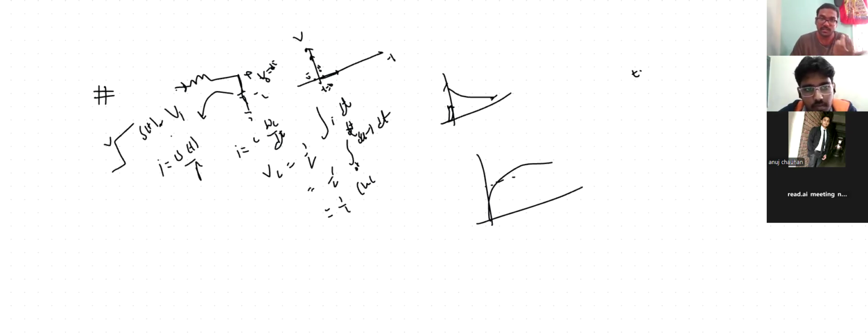But why are the responses coming different in impulse and step response? Even though at t equal to 0 the same frequency component I am injecting and the same circuit behavior is coming, meaning cap is shorting, output is seeing ground. At t equal to 0, I am saying output is seeing 0 in both cases, and the frequency component is also going infinite. In both, it is similar, but the response is different here. Why is it coming like that?